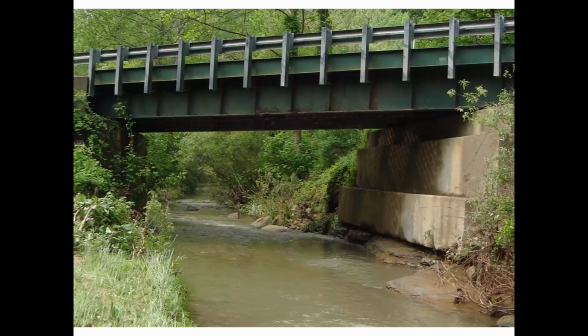Okay, so cost estimation. One of the projects that I was involved with a couple of years ago, we were doing research at bridges. And what we were doing is we were analyzing the foundation that abutments are built on. And you can see in this picture that there's a little bit of scour, that there's supposed to be rock underneath this concrete face, but over the years, as the water passes through there, especially when there's a really high flow rate, it undermines that foundation.